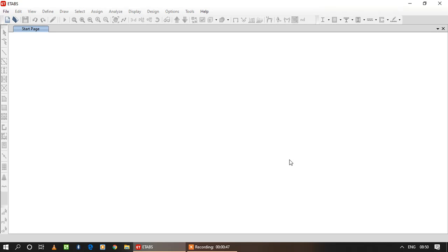Also, 3 sections of beams and columns are to be used having M40 concrete, HYSD 500 steel and mild steel as 250 for rebarring purpose. We are going to use auto select option here so that the best section will be considered by software out of C 500 by 500, C 550 by 550 and C 600 by 600 columns. Also B 500 by 300, B 550 by 350 and B 600 by 400 beams.